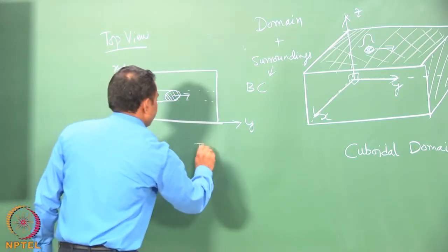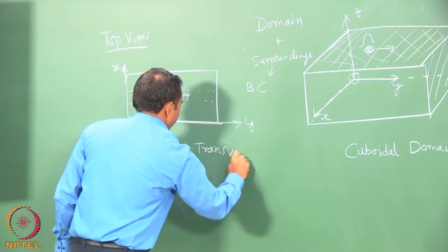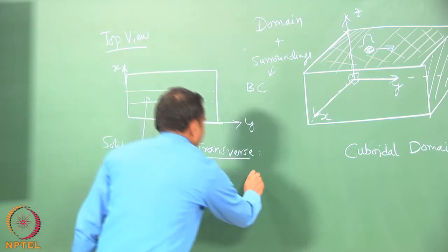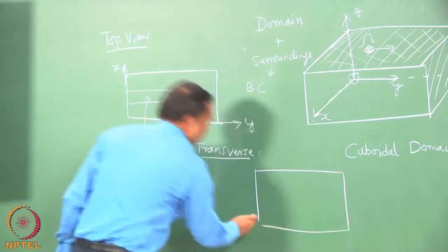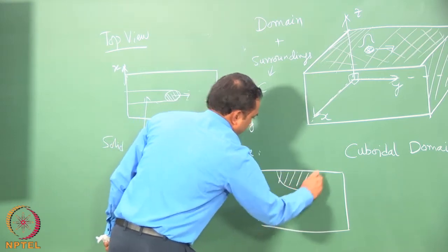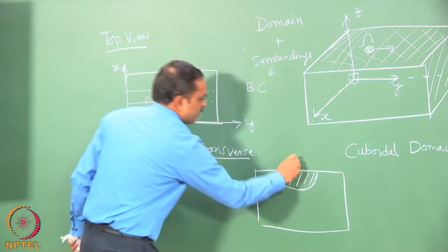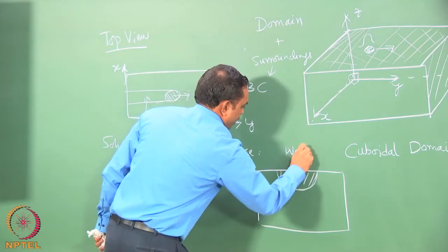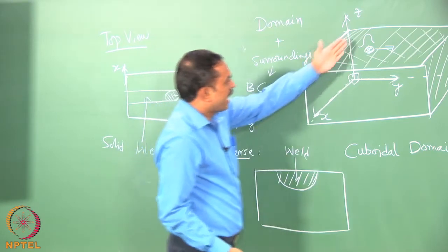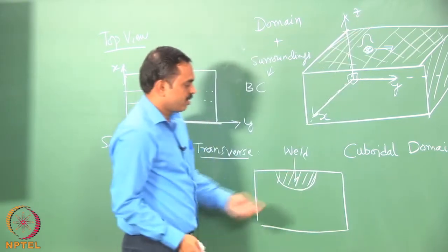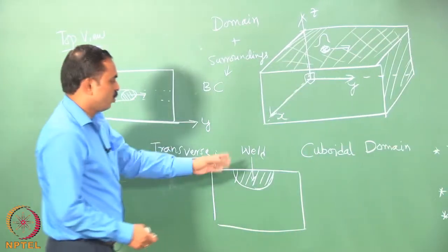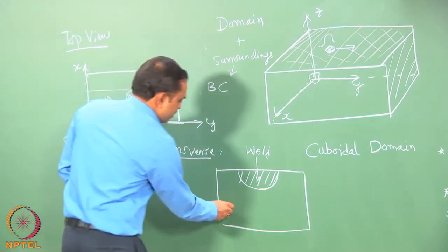And the transverse section would have this appearance. So, the solidified weld is here. If you take a section behind, and if you take a section exactly at the center of the weld, then it would be the molten pool, and when you take a section ahead, then there will be no boundary that is possible, and this is the base material.